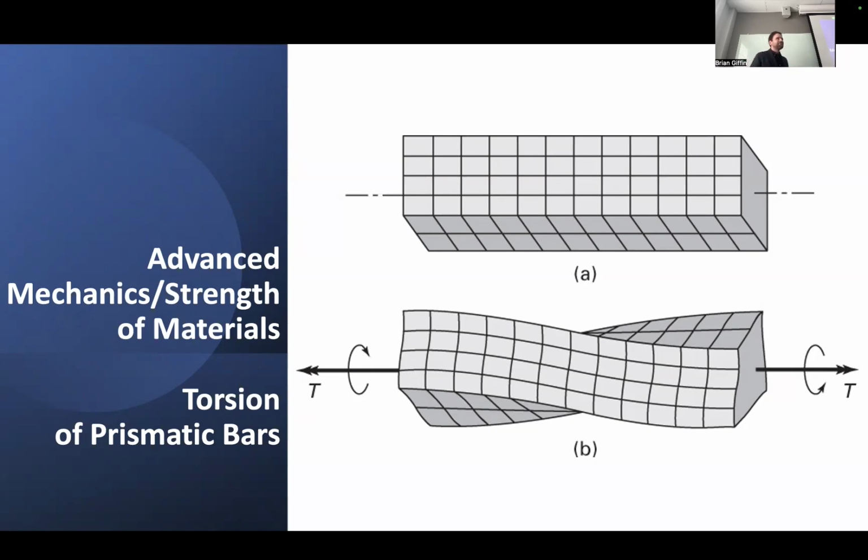And it depends on what's actually going on with respect to the shear stress distribution on a particular cross section. So if the cross section is non-symmetric, even if you're trying to apply transverse loading directly through the centroid of that cross section, that might still generate kind of like a torsional moment or a twisting kind of moment about the axis of that beam.